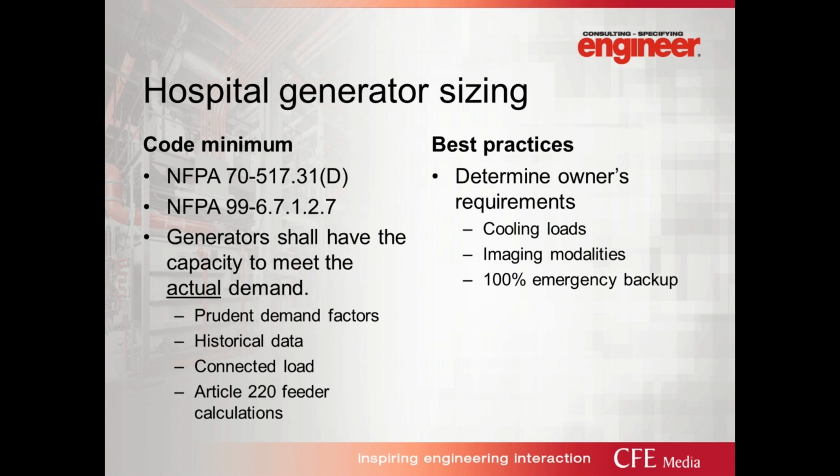The codes don't require cooling on emergency power. However, patient care cannot adequately be conducted without the proper cooling. So therefore, similar to the owner's project requirements that Bart touched on for data centers, the same thing applies in a hospital, where at the onset of the project, you have to decide what may be prudent to put on the emergency power system. Could be cooling loads, could be imaging modalities, or even in some cases, the entire facility.